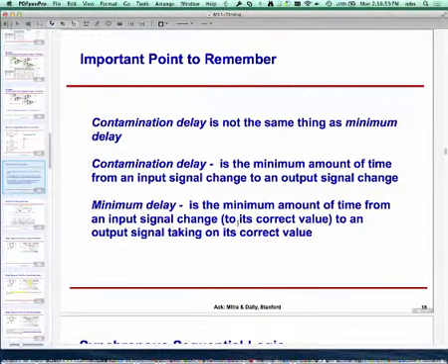So imagine temperature changes. I have different copies of the same part. Some of them may be operating faster, some of them may be operating slower. So this is giving you, across all parts, what the propagation delay will tell you, across all parts, under all conditions, what would be the delay. Some parts may see the value change and settle earlier. Or for some input data values, you may see the output settle earlier than others.